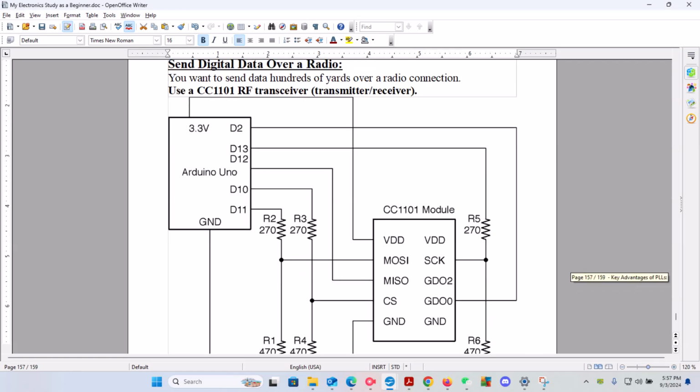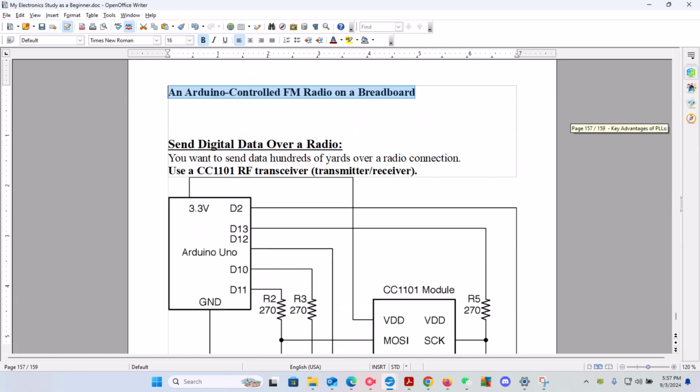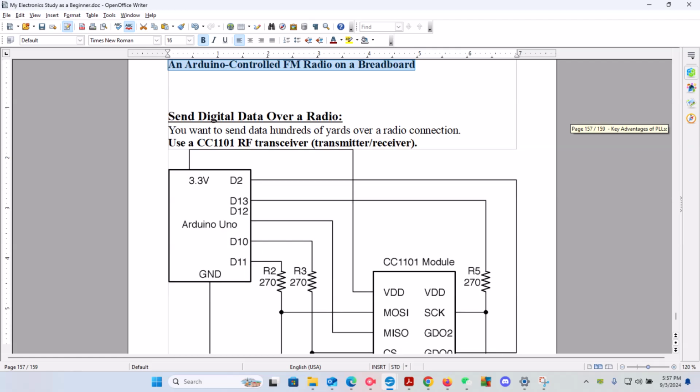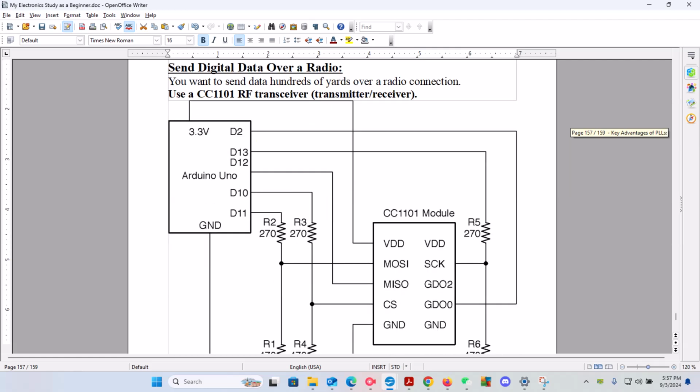And then we also notice on this chip we have diodes, denoted by capital D. So it's diode 2, diode 13, diode 12, diode 11. The purpose of them, as I said in one of the earliest of my videos, is to redirect or control the direction of the current flow. So with diode 2, if we logically follow the line, it's going to the chip pin called GD00.